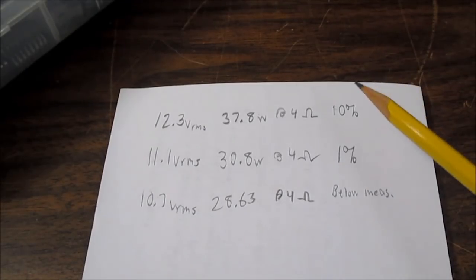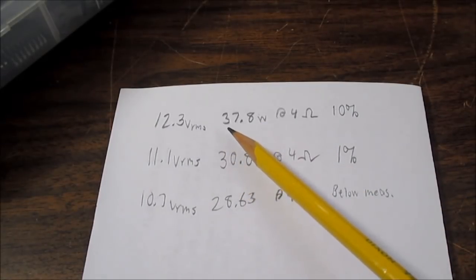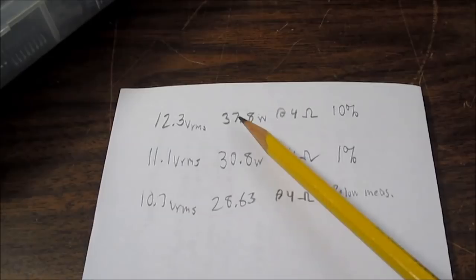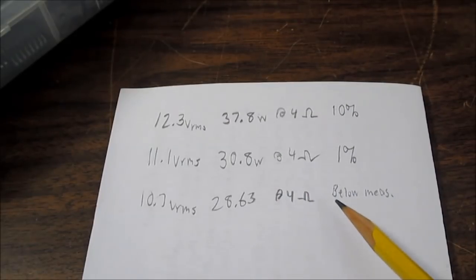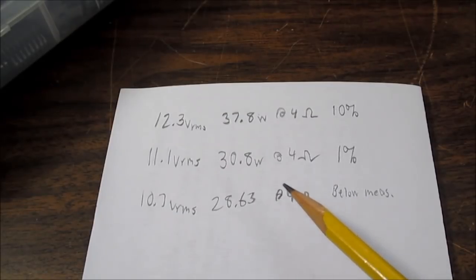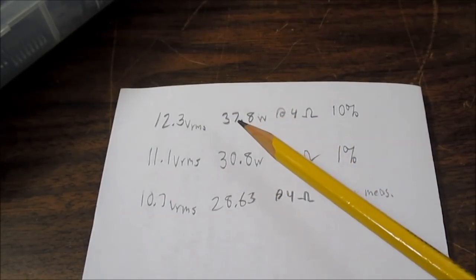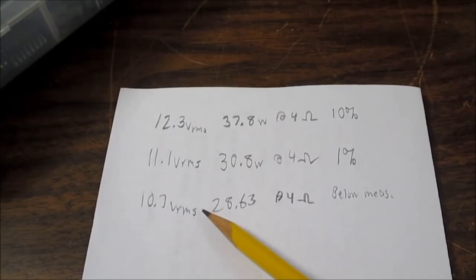So in summary, at 10% distortion with the amplifier well into clipping, we're getting almost 38 watts. That makes the numbers look nice and high compared to just 28.63 watts before clipping. In other words, there's not any significant distortion. So yeah, they're just propping up the power figures of the amplifier by using that 10% number. To me, it doesn't make sense. It makes the chip or amplifier look bad when you do that. I would rather see pre-clipping figures like this.